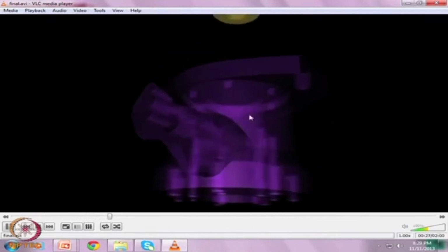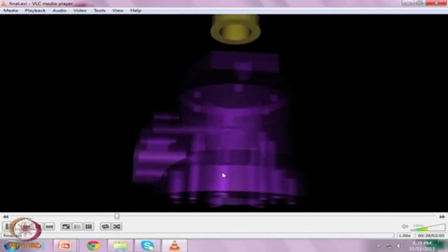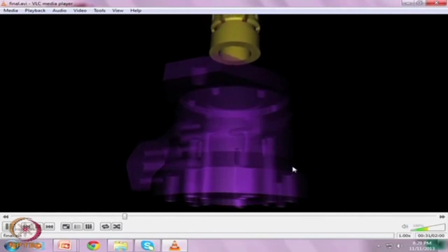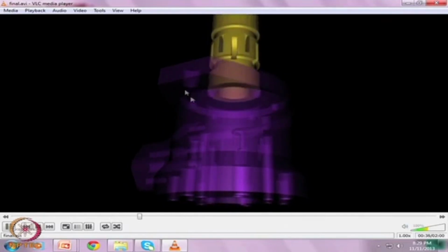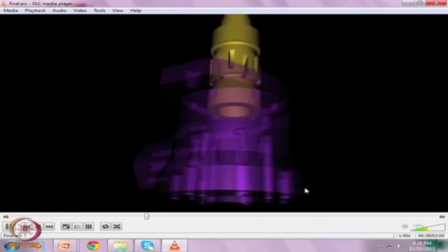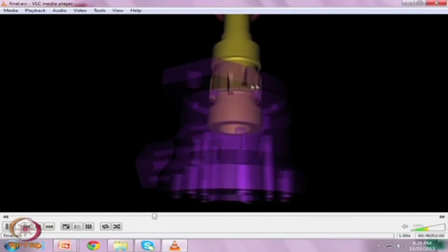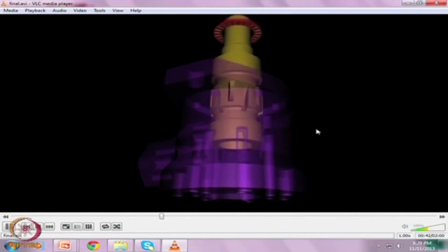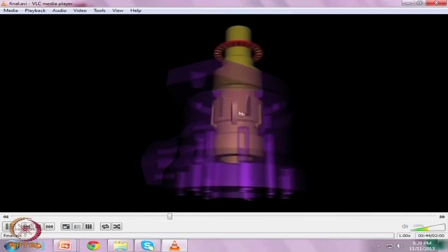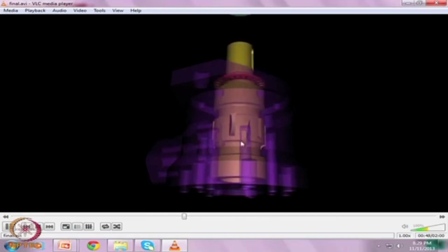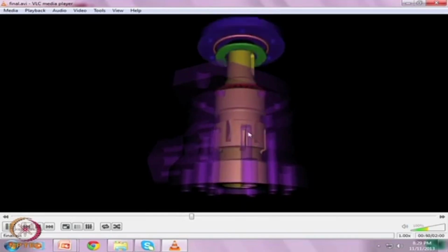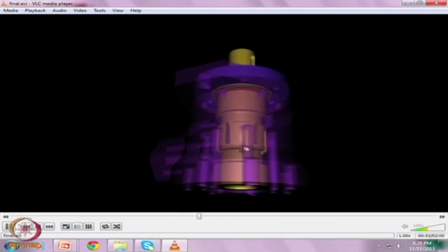You will find 7 such long holes, as well as 7 such short holes for fixing the star ring, etc. Now, look at the distributor valve which is coming in. You can see these slots and grooves are like this, and at the mid position, this common portion will match with these grooves. If you look into this, this is matching.